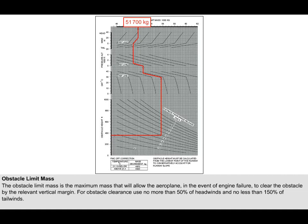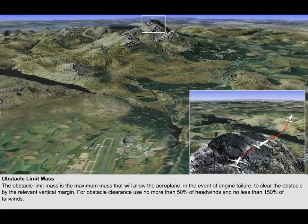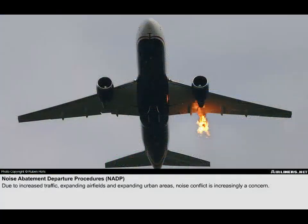However, if this mass unduly restricts the takeoff mass, then the aeroplane may be dispatched with a greater mass, so long as the aeroplane turns around the obstacle, clearing it by the relevant horizontal margins, and does not exceed the turn restrictions when trying to do so. There is only a remote or very remote chance that an engine will fail on takeoff, and therefore meeting the climb gradient and obstacle clearance requirements will not be a significant concern.